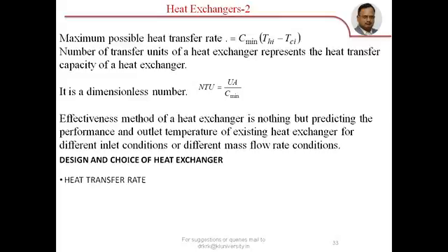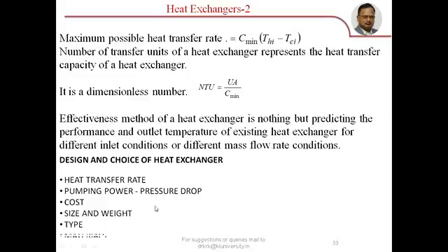So in case of design of heat exchanger, we have to concentrate more on maximizing the transfer rate, minimizing the pumping power or pressure drop, and minimizing the cost of the equipment, minimization of size and weight, and what kind and type of heat exchanger we have to choose, and what different materials we have to select for the tubing or for the shell, etc. These are the design considerations in the selection of a heat exchanger.